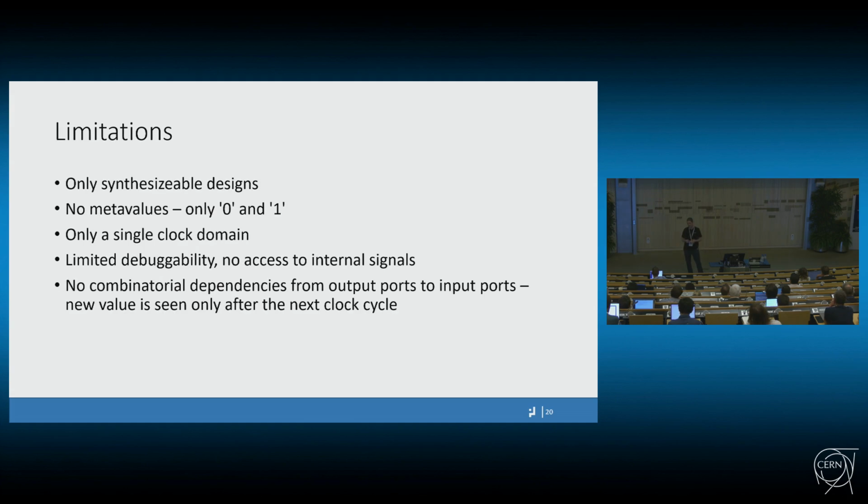Some limitations, obviously: for the design to be synthesized, it first needs to be synthesizable. And with this co-simulation system, you can only simulate synthesizable designs. In the hardware, there are no meta values, so only zeros and ones are supported.